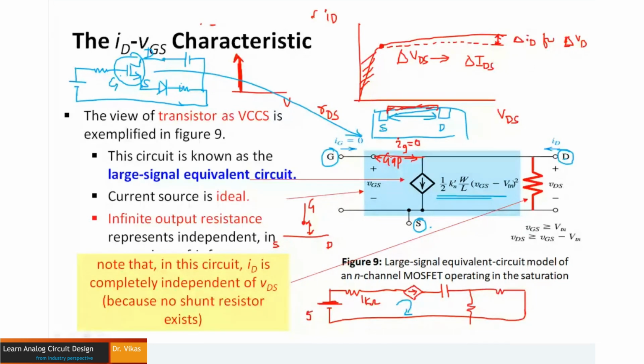So this entire small incremental change of Vd, whenever there is a small incremental Id beyond a particular voltage of pinch off, that means during the saturation region, I can say that there is a small resistance observed, and that is modeled something like this. So this is basically how your entire modeling of your MOSFET looks.